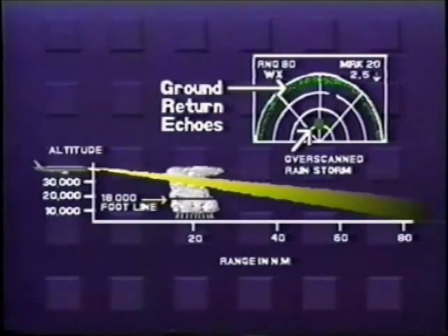With a little practice, you'll be able to set up a display range very quickly. Letting the radar beam overscan a storm which is off to the side of your flight path is okay. It is, however, ill-advised to fly through the clear air above a storm cell or penetrate the less reflective storm top. That area of the storm can be very dangerous due to unstable air and the possible presence of hail.